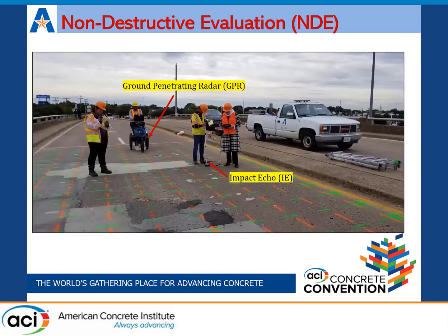As part of non-destructive evaluation, ground penetrating radar and impact echo were used. With GPR, we determine rebar depth, location, and spacing of the rebar in the concrete deck. And with the help of the impact echo device, we detect the delamination of the concrete deck.